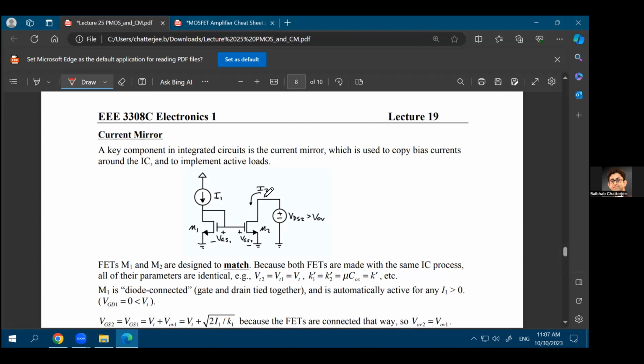Now, the problem of biasing transistors using voltage is that voltages are noisy, because there is a lot of noise in any voltage that you can probe in a circuit. If you looked at voltages in a circuit using an oscilloscope, you might have seen that there is a lot of noise at any point. It can pick up more noise depending on the resistance at that point. If the resistance is high, it can pick up more and more environmental noise. So that's one issue with voltages. The other issue with voltages is that there is always an IR drop. There is something called IR drop in any kind of circuit.